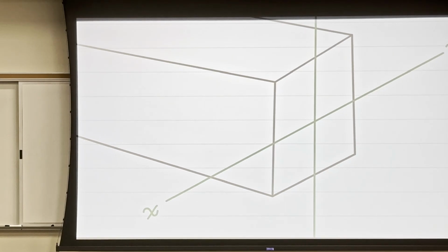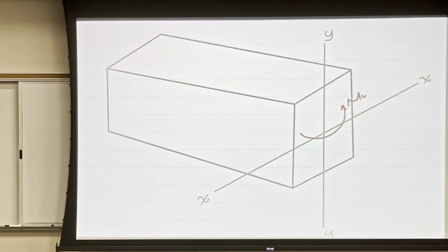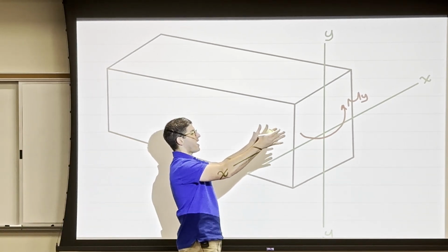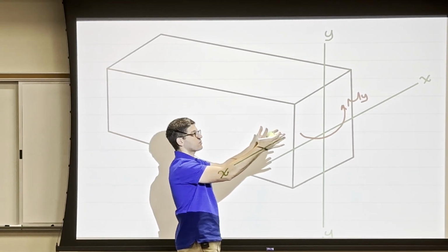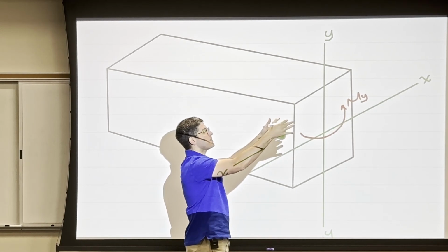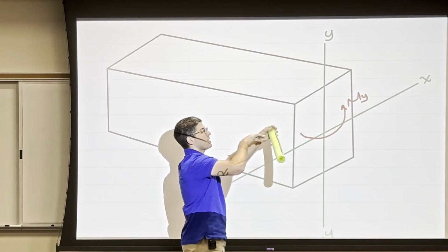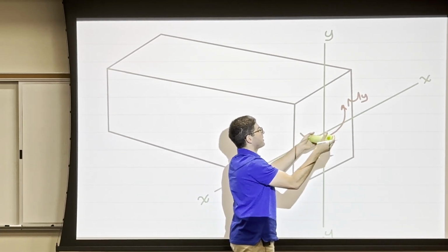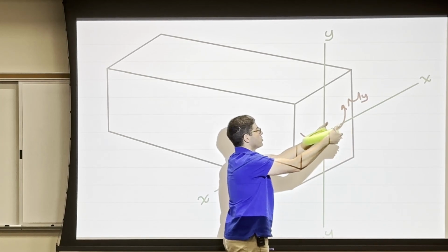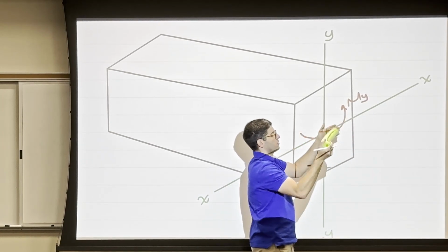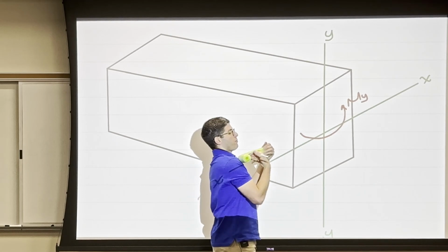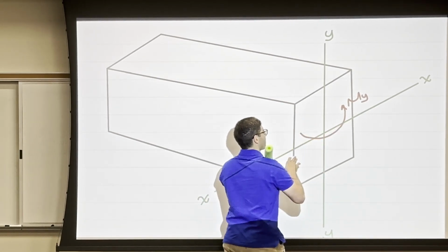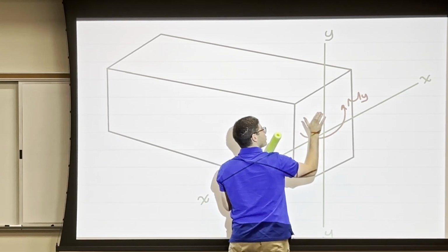What if I have an my, which is moment around the y-axis now? If I have this beam, when I apply mx, which is moment about x, this beam is going to bend around the x-axis. But when I bend it around y, for example, if I apply a moment that way, this side, if you look in here, is in compression, and this side is in tension, which is what is shown here. So if I apply a moment here, let your fingers follow the moment.